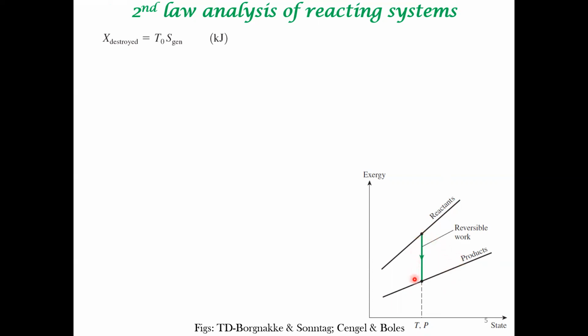And this exergy change is associated with entropy generation and some exergy destruction. We can also correlate it to reversible work. So let's see how we are going to think about all these things. It's good for you to refresh how we looked at exergy analysis of a steady flow system.